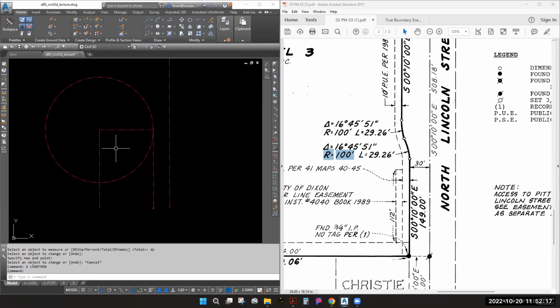So when edge mode is off, I can't trim any object in which the cutting plane doesn't fully go through that object, okay? If my edge mode is on, 1 meaning on, and I use that line to trim, it allows me to trim off what I don't need.